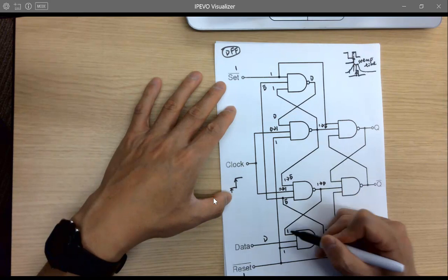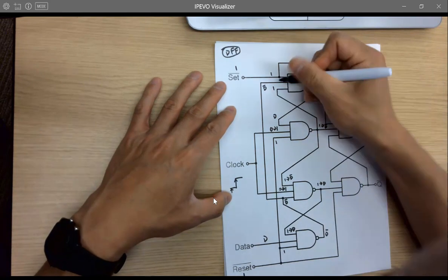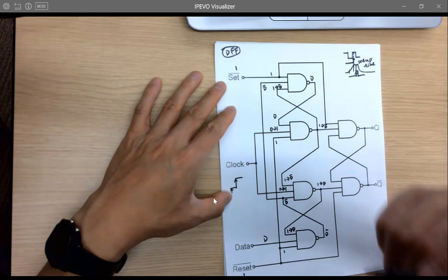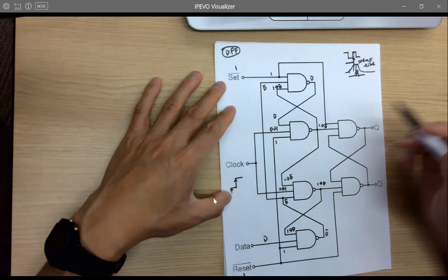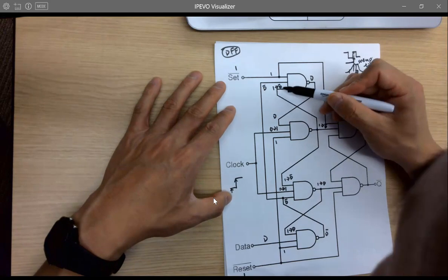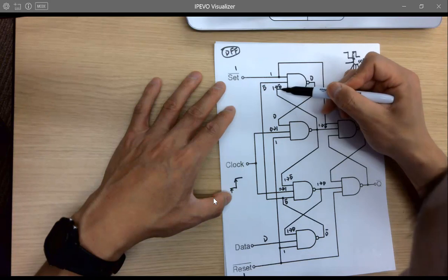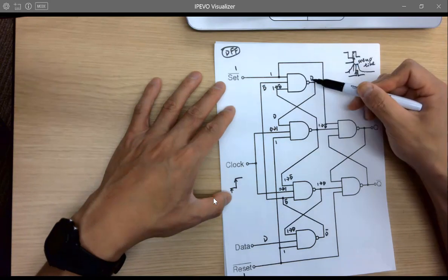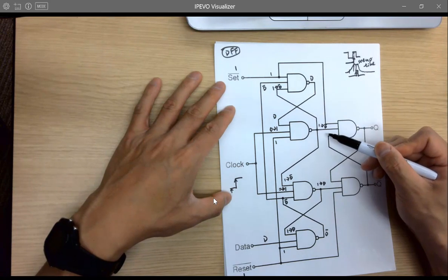And this will be changed to D, it's the same signal line, and the same goes for this one, which will be changed to D bar, right? Okay, so this becomes 1 D bar, right? Which is D. So D comes back here, D11, still D naught, so stable.